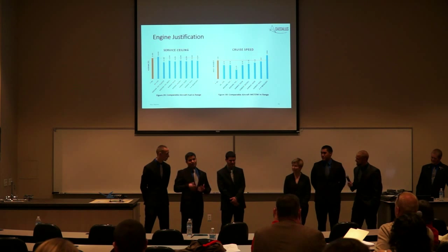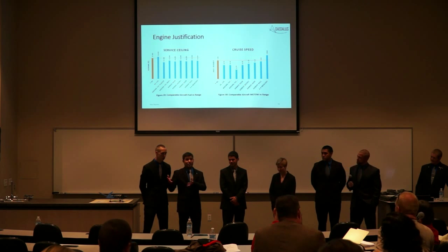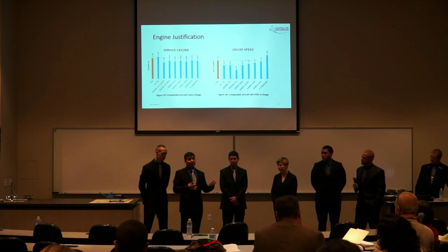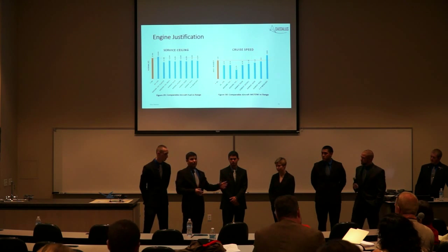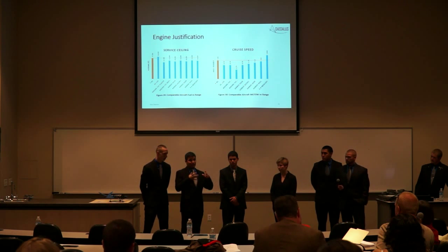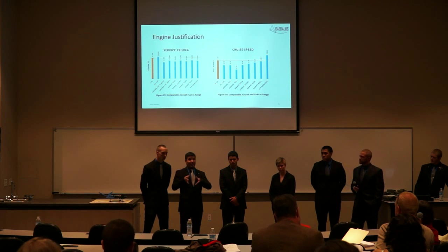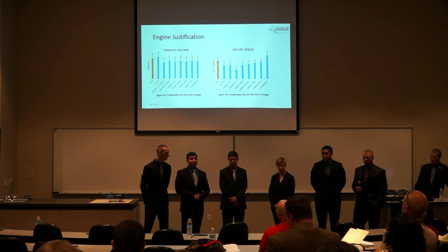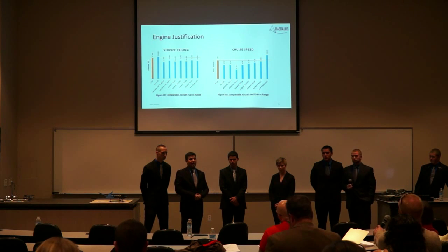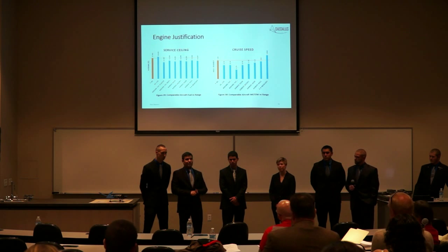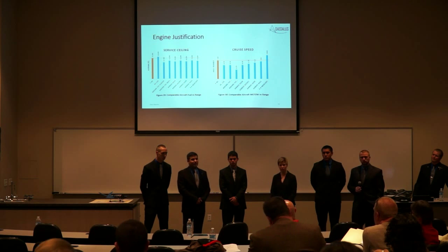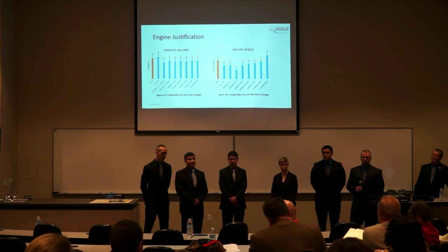That would just create extra drag on that side of the engine out area, but we don't know the drag of the inlet yet. We assume some losses for the engine, but we don't know the drag in the inlet completely. And that's part of our wind tunnel testing that we're going to be doing next semester. So we will calculate what happens if you have no suction, what's the max drag that you get from that inlet, and we can add that to the drag created by the engine in the engine out scenario.